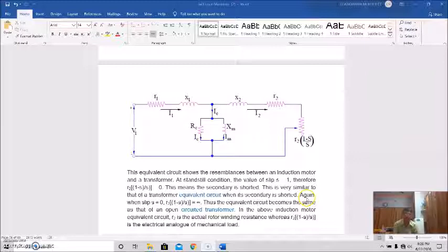Okay, so with this, I think we are ready to complete the equivalent circuit discussion of the induction motor. I hope all of you have understood this. If you go step by step through the development process of the induction motor equivalent circuit, keeping in mind its resemblance with the transformer, with the little difference that it is a rotating device and the transformer is a static device, then we developed first the stator circuit model, then the rotor circuit model. Then we combined these two. Before combining, we took the rotor circuit model to the same supply frequency. Then we have combined